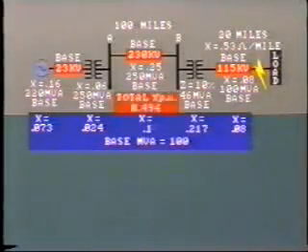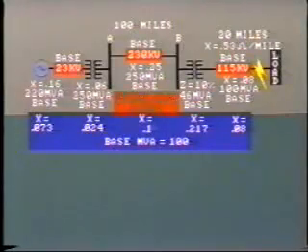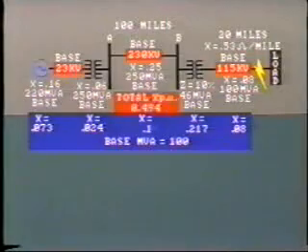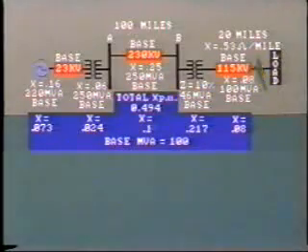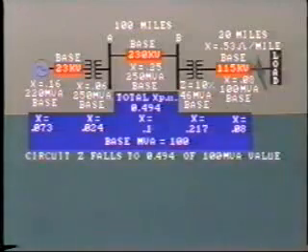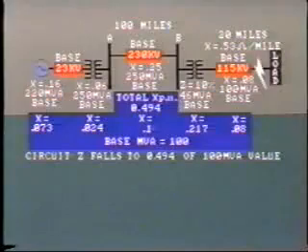Well, as the fault is at the end of the line, summating gives us a total per unit reactance to the fault of 0.494. And remember, this is calculated on a base of 100 MVA. This means that when a fault occurs on the end of the line, the circuit impedance will fall to 0.494 of its value at 100 MVA load.